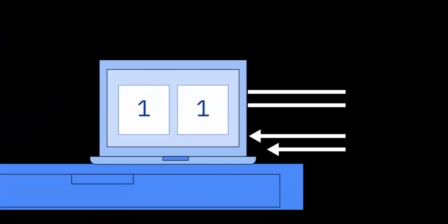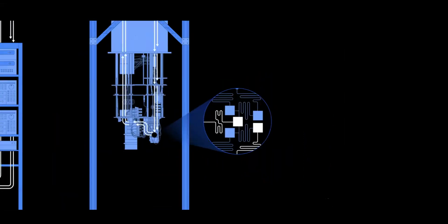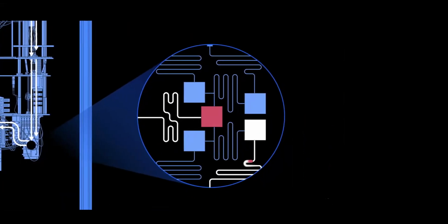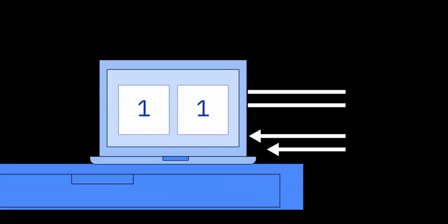So basically, we'll watch it one more time, I guess. The main thing that happens is we ring up the readout resonators that are connected to the qubits, which collapse the state, and they impart a state-dependent phase shift on these signals. These signals then leave the qubit chip and are amplified using some very special amplifiers I'll talk about a little bit later, and come out of the fridge, and they are then large enough signals. They go from tens of photons or something like that to a signal that you can measure very easily with a computer. We mix it down to an intermediate frequency that can be digitized easily, and we integrate and discriminate them so we know what the measurements actually are.